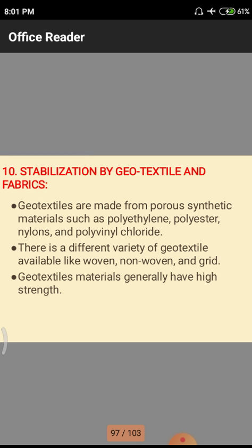That means huge amounts of temperature, floods or wind force are acting on the structure. So due to those forces, there may be some decrement of strength of the soil. To overcome those kinds of situations, after the densification is over, we have to go for this geotextile process.